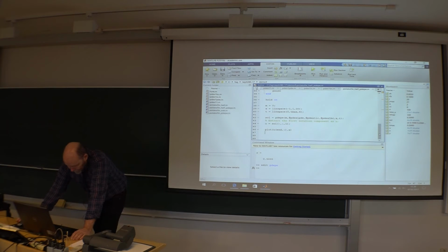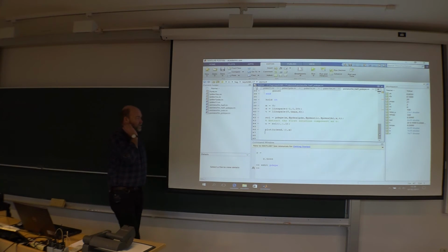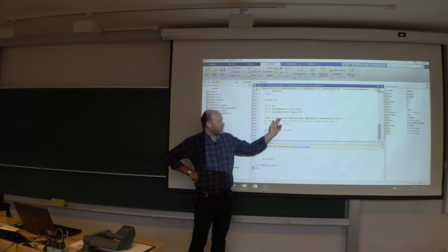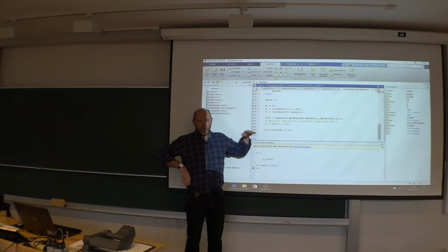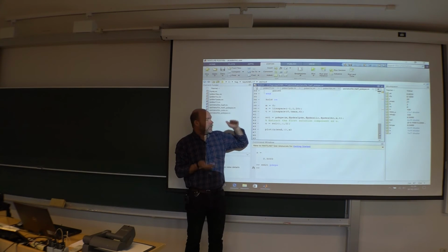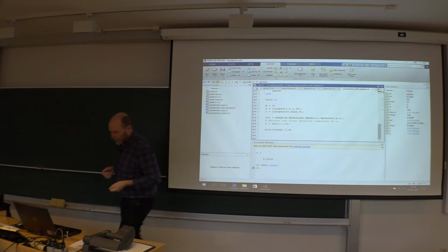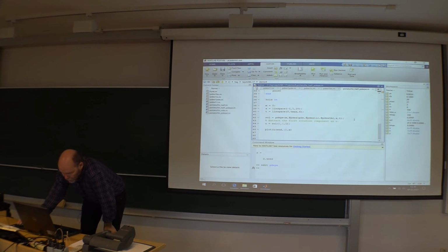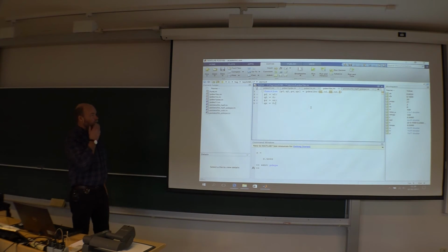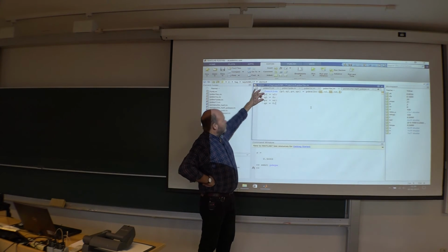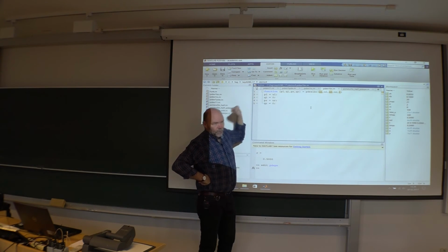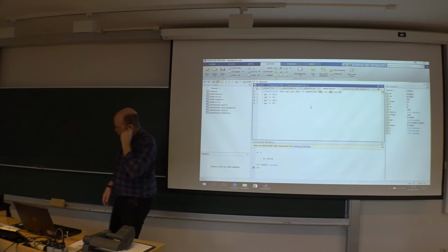Like that. Now I have to change the setup for this function pdepe. He was originally now taken to be from -1 to +1. Now he's going from 0 to 1. And I have to change the boundary condition as well. So here is now the boundary condition. The first one should be the same. Now the second one should be derivative equal to 0.